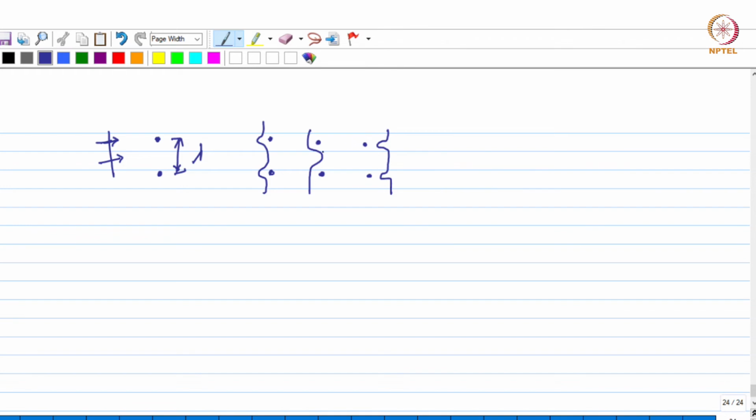But while bending around these particles, the dislocation line is actually leaving a loop around it, like this. And since these two portions of the dislocation in this loop on either side of the particle are of opposite sign, they will annihilate each other, and as a result of that, these loops will be left behind and the dislocation line will continue to move.